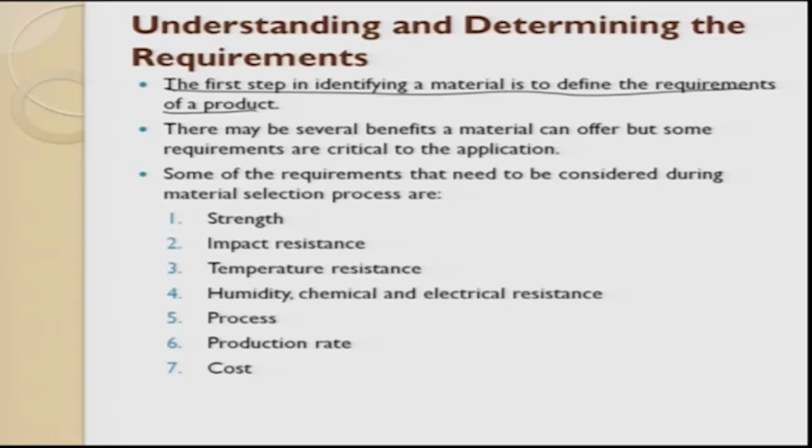The third thing is roughness. It has to be as smooth as possible. The fourth thing is when you sit on a chair, we sit as an impact load. When you sit as an impact load, the chair has to take impact load also. So the toughness should be high. Now you see, we thought initially it is compressive, but now you see a list of properties are required. Mechanical properties are required from a product. And then on top of it, the other things are the color, the texture, all these things play an important role.